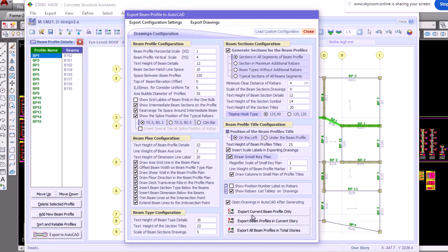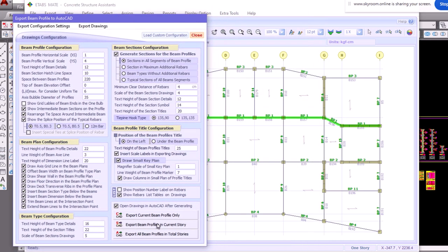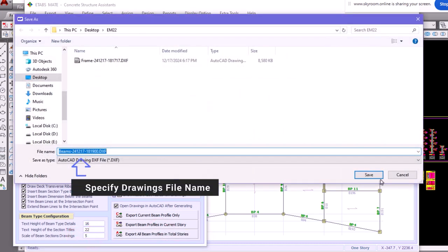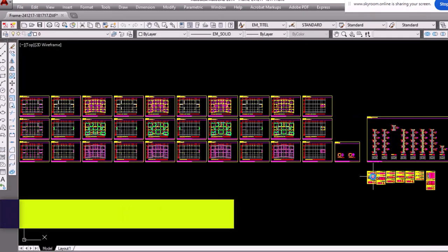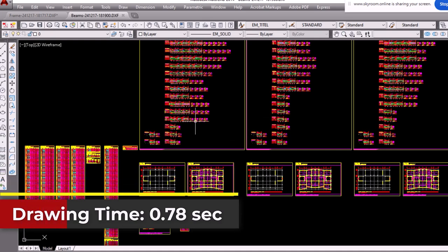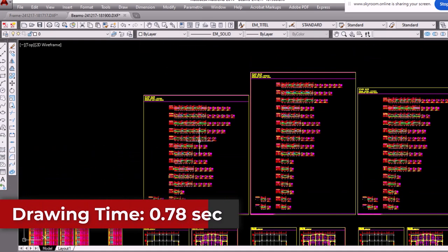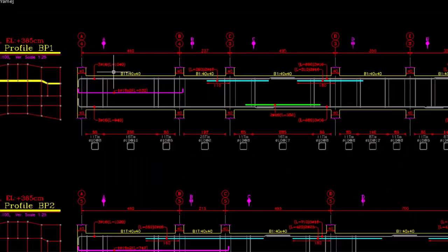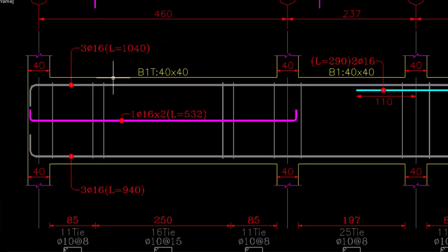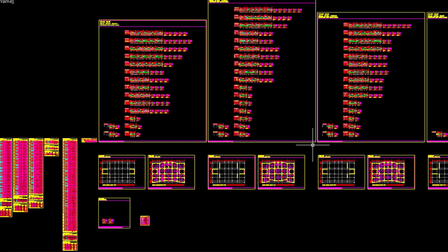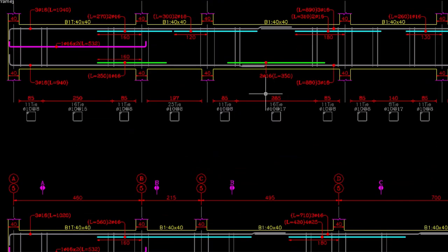When you select the slab within the system, you will immediately observe that your detailed drawings are generated in under a second, and these precise drawings include complete information, specifically all the various bar types, continuous reinforcement details, top reinforcement specifications, bottom reinforcement placements, splice locations, stirrups, and in fact all the beam details are clearly presented here.